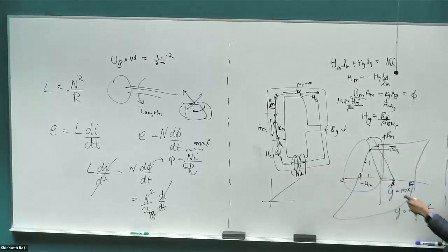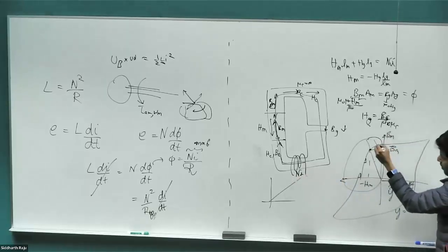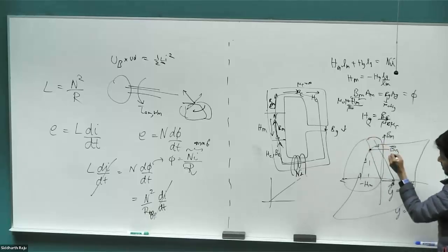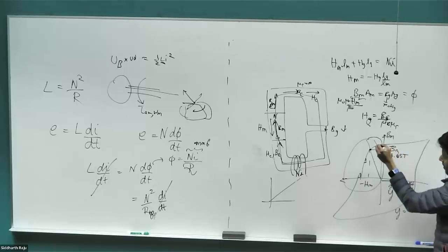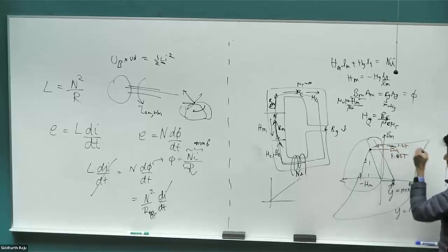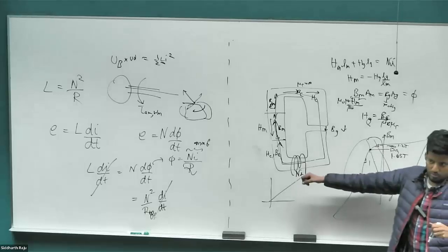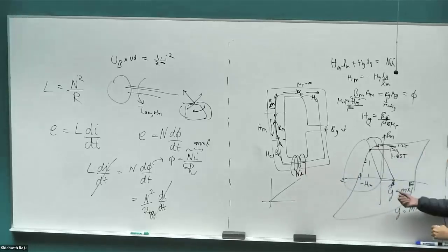You can do the reverse calculation. Draw a line to, let's say I want the B field without the coil is 1.05 Tesla. But I say I want actually 1.2 Tesla in the air gap. What current should I pass through this coil? Right? It's a reverse problem.